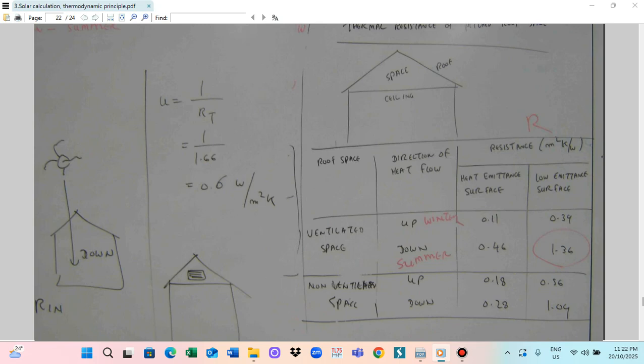So the first thing when you calculate for a particular roof or building structure, you have to sketch what kind of materials are included. For the roof, what material; for the wall, how many brick layers. Then you have to calculate the R value for the individual material. So I give you the table. Those are the typical tables we use in the field. You can use them for brick, insulation or timber structure. You can calculate the R value.